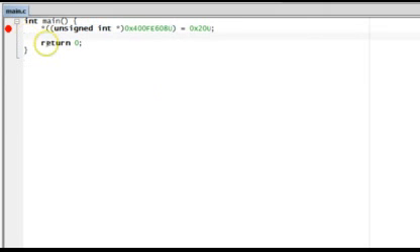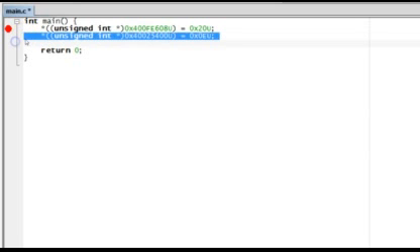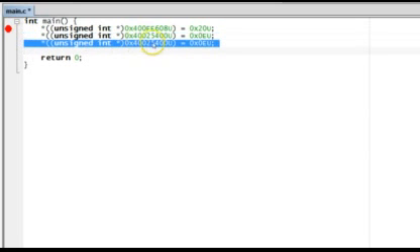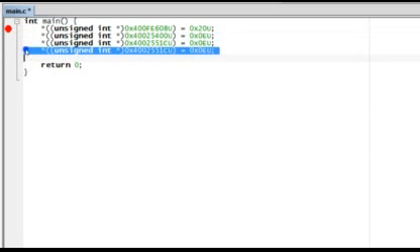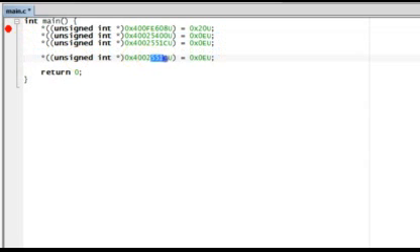Alright, so now you can press on with the next register, which is the GPIO-F pin direction register, where you need to set bits 1, 2 and 3 by writing hex E. Finally, the GPIO-F configuration requires also setting bits 1, 2 and 3 in the digital function register. With this done, you can turn the red color LED on and off by setting and clearing bit 1 in the GPIO-F data register.